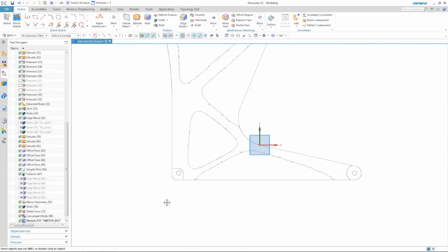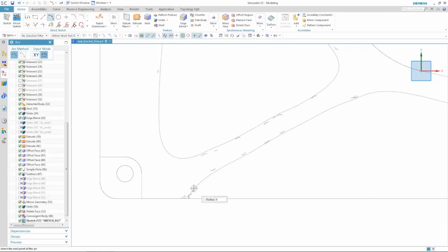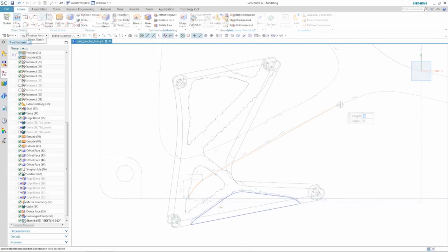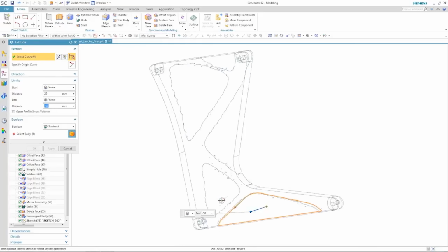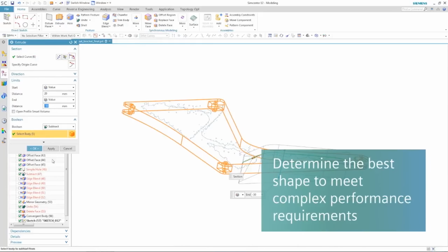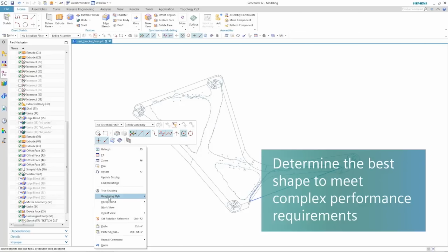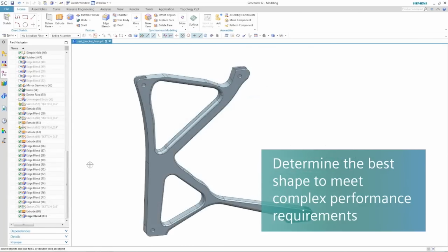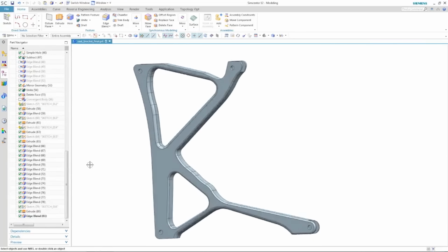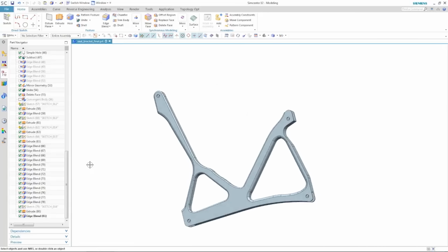And then we can go ahead and in the software correct the deformation and create a predeformed geometry that we can then print on the machine, and it is turning out correctly. And with that simulation then, you know that this is going to be the best version of this available using the machine you used. Exactly, and you want to minimize the risk of failures during the printing process, because that can cost a lot of time and money.